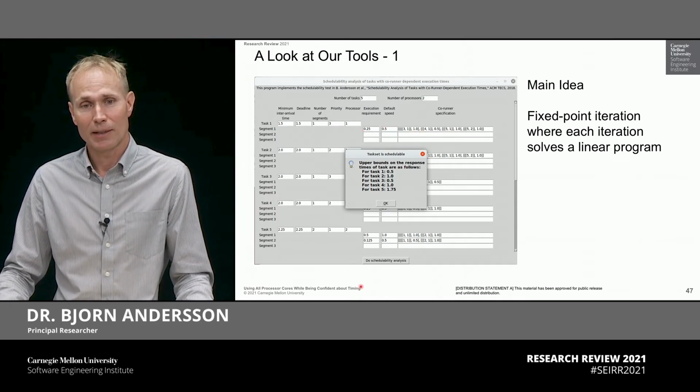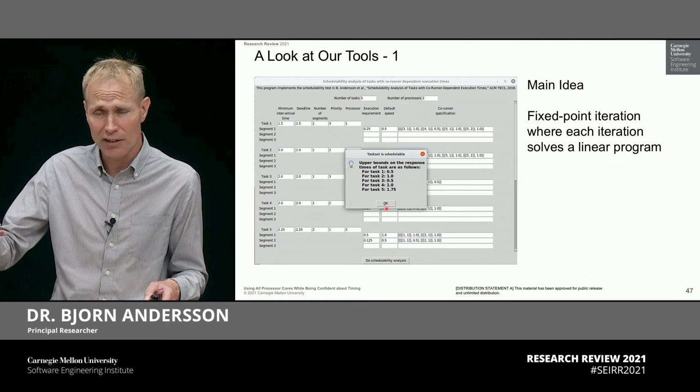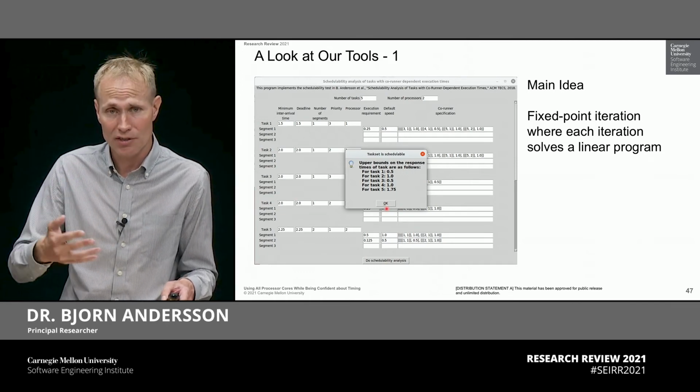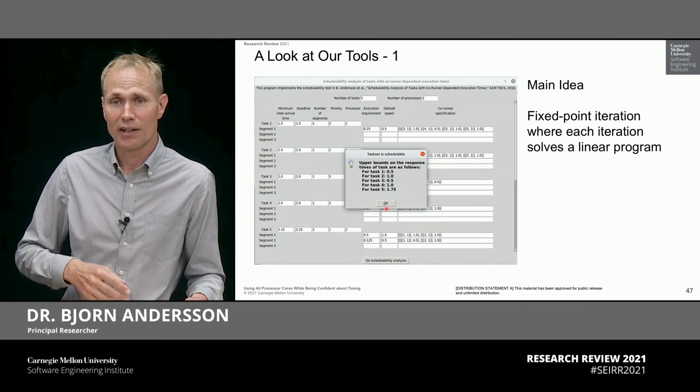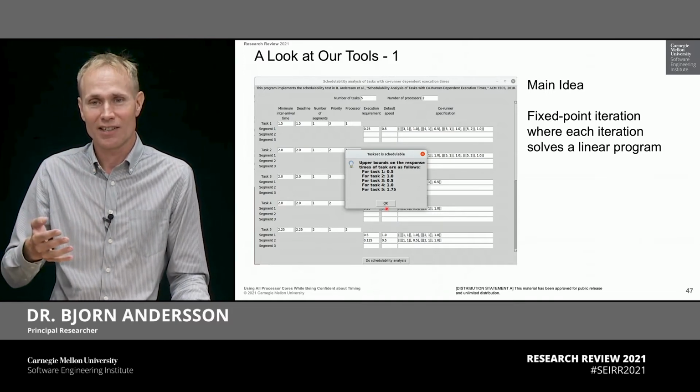And then you can just click the button here, and it will tell you if this system is safe from a timing perspective. It will tell you schedulable or unschedulable. Schedulable means that for all scenarios, it will meet all deadlines according to the assumptions, and it will also output the response times.